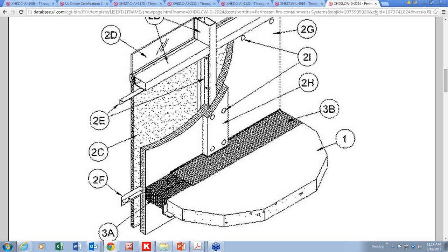And what happens is, if there's a breach in that thermal barrier, or if there's no thermal barrier at all, and there's a fire on the exterior skin of the building, somebody throws a cigarette butt in a garbage can or a dumpster on the perimeter of the building, that fire starts and gets inside the curtain wall assembly where there's foam insulation, and it can then catch fire. Google, if you want, Tamweel, T-A-M-W-E-E-L, Towers in Dubai, October 2013. Exact same thing happened. A cigarette butt started a fire. Good question.